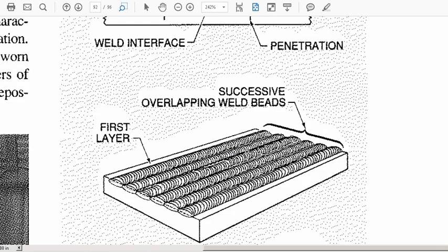Now another specialty weld type is the surface weld. When might you actually do a surface weld? Well, that would probably be on some repair jobs or some jobs where you're actually trying to protect a surface from wear. Could be an abrasive environment, and you're essentially building up material on top of the base metal. So you're taking something that you have and you're technically either repairing it. For example, maybe it got worn down through the elements, and you're going to build a layer of material back on top of it, or you're going to use this layer of protection, which is going to make it thicker over time, to actually protect it from some type of situation.